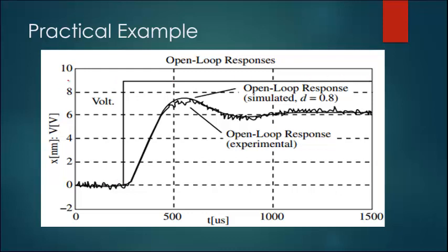It has a value of 9, and we have this graph showing the practical response and the simulated response. We can see that there is a lot of jittering in the response we get from the experimental data, and that will always happen in control systems or electrical systems in general. Why? Because the data has a lot of noise and disturbance, so you can't get smooth data. You can use filters to get a better result.